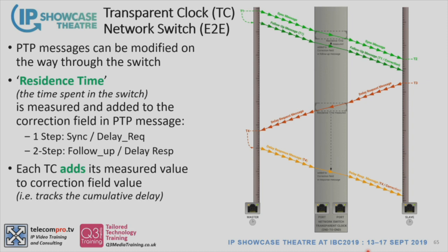But the whole point is, if you don't implement it accurately and you do get variance, that variance could increase over all the network steps. So if each of these transparent clocks didn't accurately do its job, from the top to the bottom, if you had 5 layers of boundary clocks and transparent clocks in there, you could insert more and more variance, and you might end up with big problems. That's where a lot of projects have had trouble, and a lot of the test and measurement people have got various tools now for looking at that jitter on the PTP. And again, it's modifying the values as it comes through.